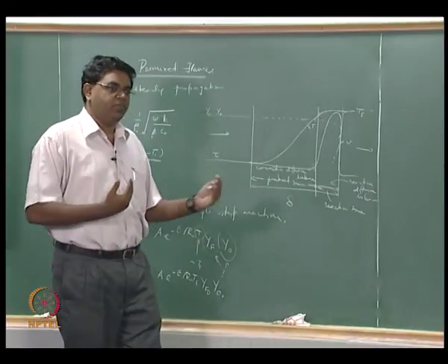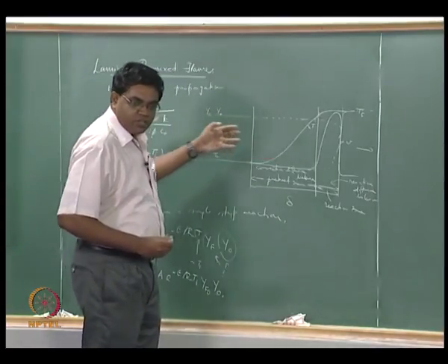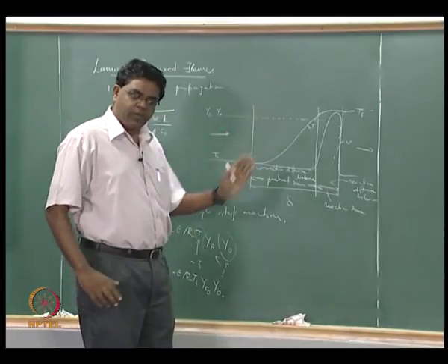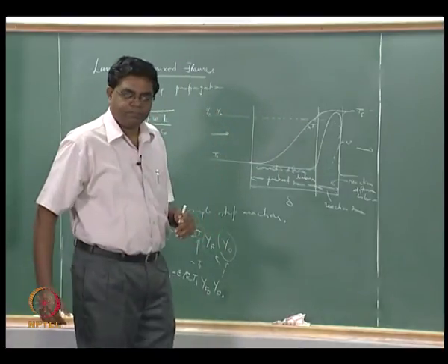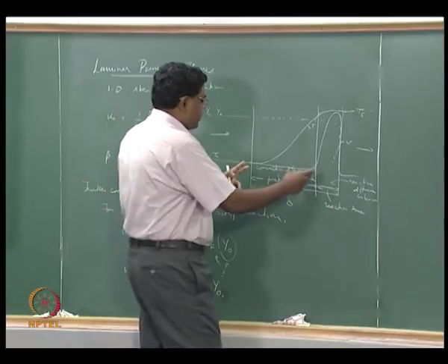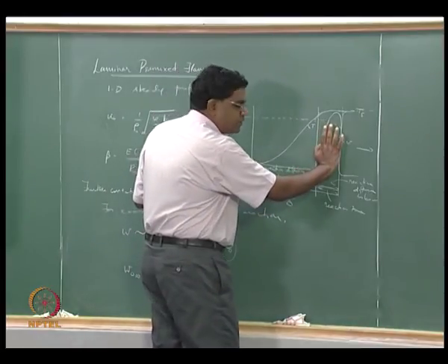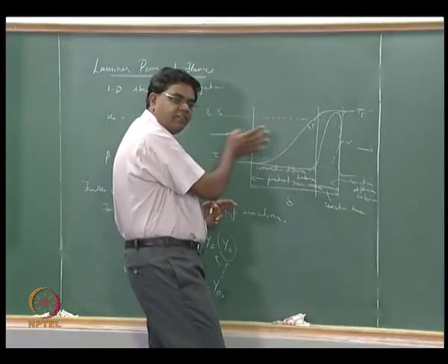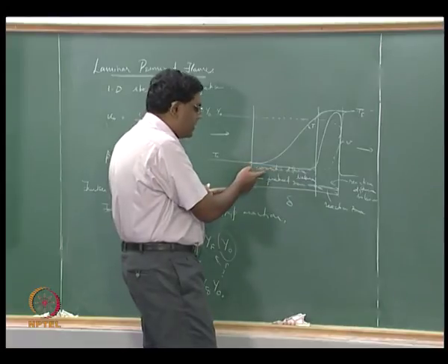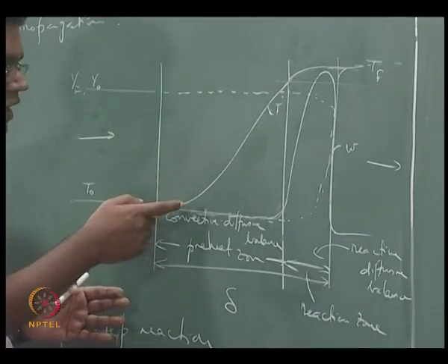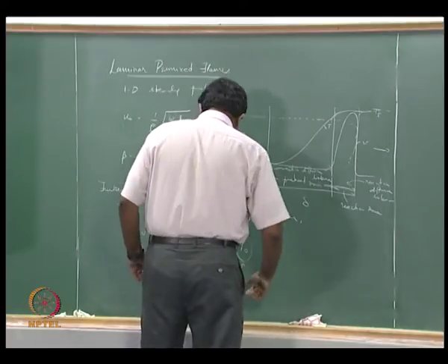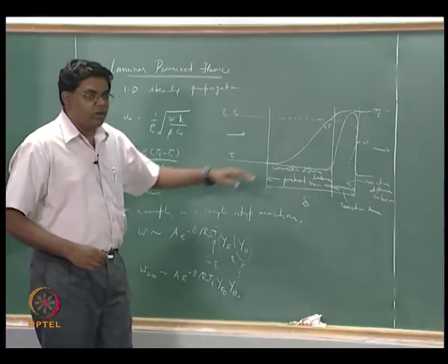So you now have a competition between convection of the flow of the mixture on the whole, and typically you are always thinking about convection for a mixture, okay, and upstream diffusion of the products. So sure enough, in this place where you do not have reactants happening, you had a lot of products that were produced here, you now are witnessing an incursion of products because of an upstream diffusion against the convection, and there must be a balance between these two, which is exactly the same as what we talked about for the energy balance, which is a convective diffusive balance for the product species mass, right.